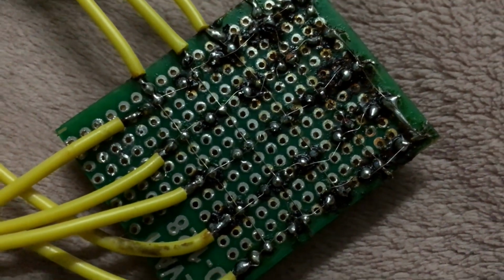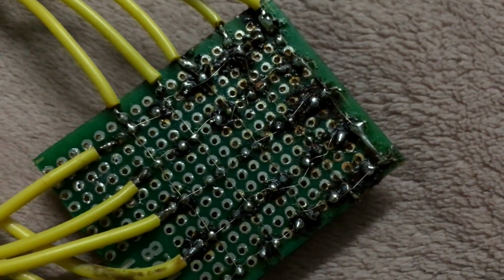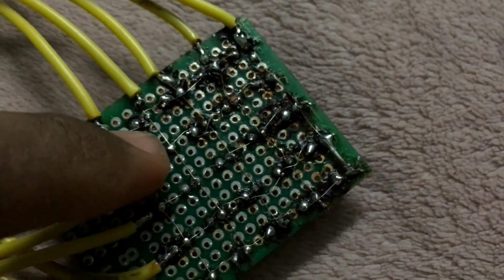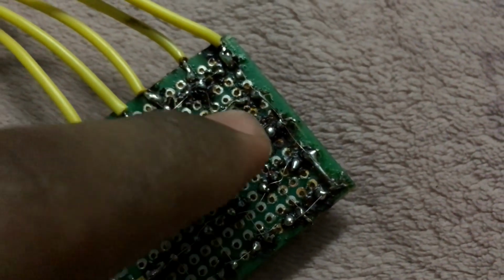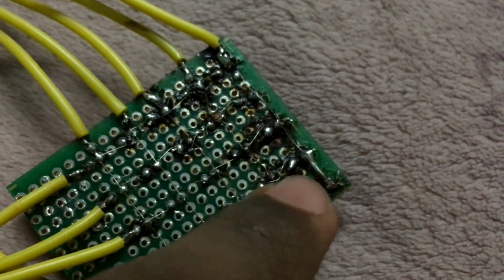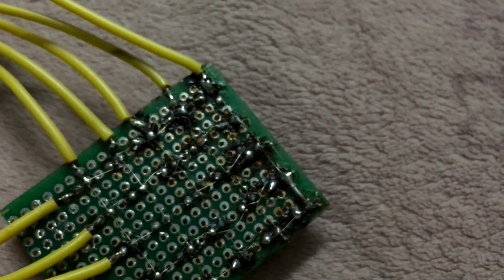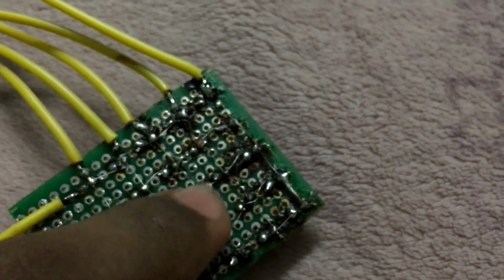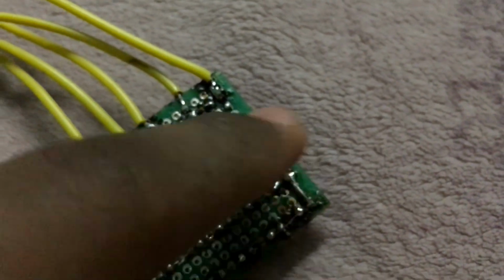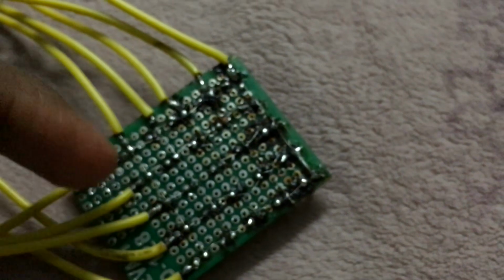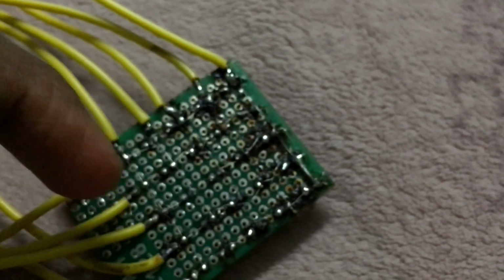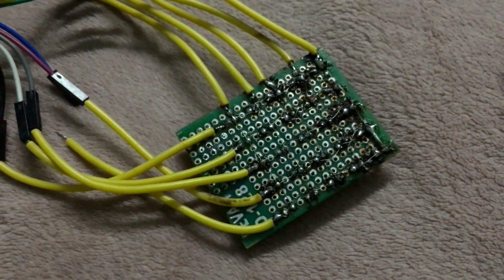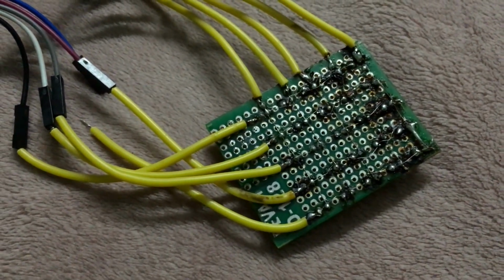For example, if you need A to be displayed, what you should do is turn on this one, this one, this one, this one, go here, here, here, then turn on this LED, this one, and finally this one. After that, turn off everything, then you display this small line here. So it is A, it comes like this, and that's how we are going to do the program. Based on this logic, we are going to write the entire program.